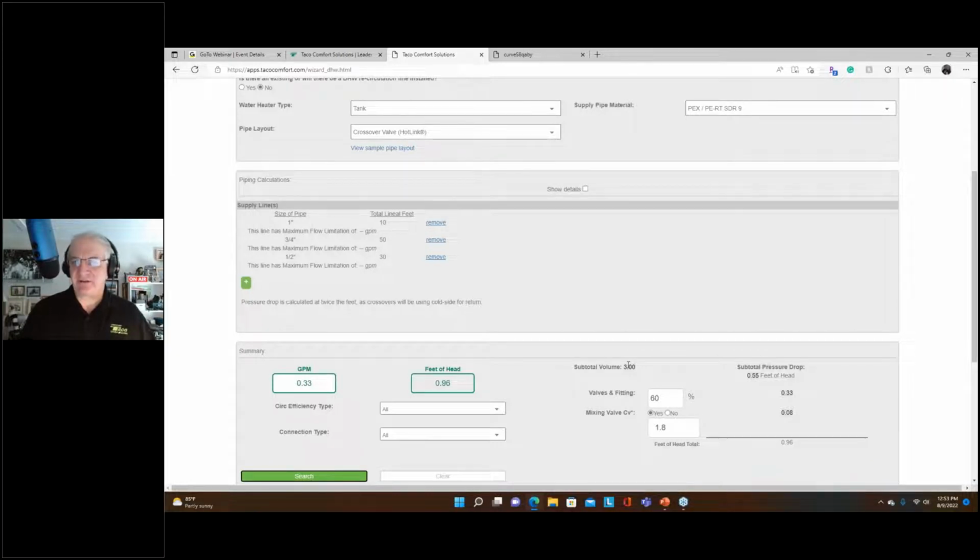Now with our 5 minutes on, 10 minutes off, by the first cycle we've got this thing primed and ready to go. Whereas in that larger house, it might take 2 cycles to get it primed and ready to go. So again, the value of insulating the pipe, the value of understanding how many gallons of water you have in that piping system, and how we're going to work with that, that's going to be the important thing. We want to make sure we get that hot water to that last fixture in a timely manner, but in a timer type of system, time is on our side.